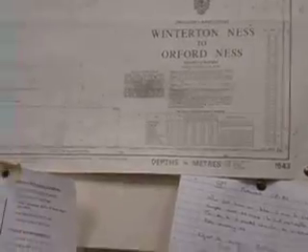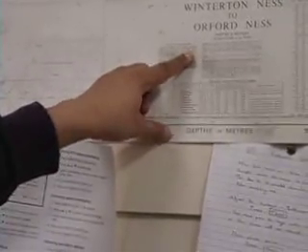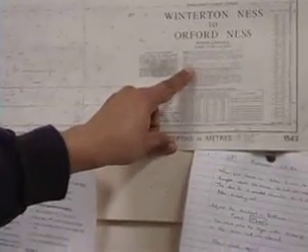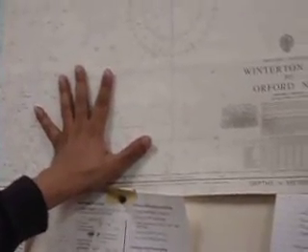If you choose WGS 84, you have to put this much correction. But this chart is drawn or referred to the Ordnance Survey of Great Britain 1936 datum, because this was published in 1994, 20 years before. So it is not updated, because this is a very old chart.